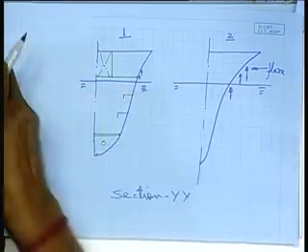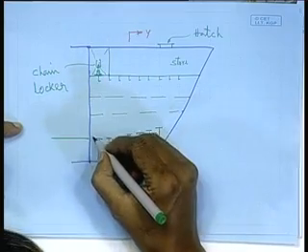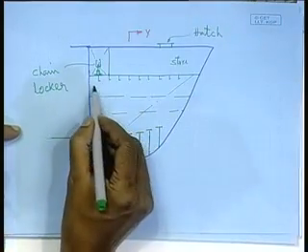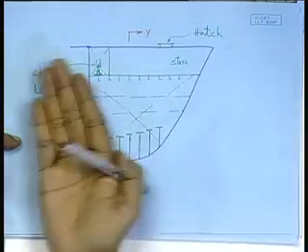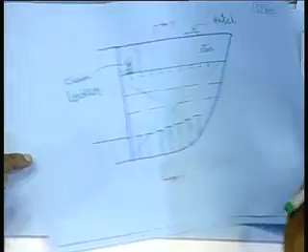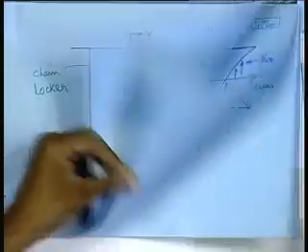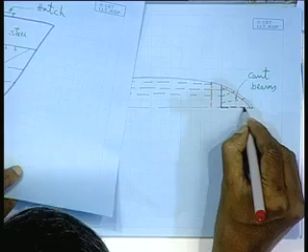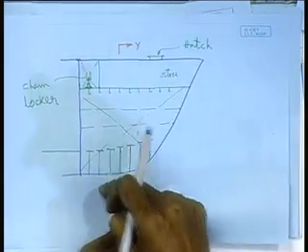Then what about these spaces? What happens is, depending on the requirement, one can have even a centerline bulkhead, a centerline wash bulkhead. This I have drawn. That means there is a centerline bulkhead, a plate here in the center line, right. That means that will be visible. Well, this one here, the red dotted line, this is my centerline bulkhead.